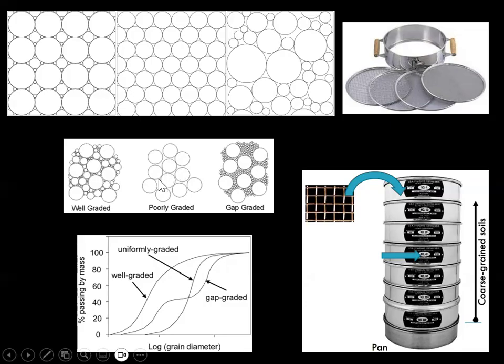So if only we could fill these gaps with more aggregate. We just need a different size aggregate, right? Couldn't you put medium-sized pebbles in there to pack that? But if you zoom in on that, sort of like a fractal animation, now you run into the same problem an order of magnitude down. Now you've got gaps between those gaps. So do you see what this is leading to? You really want a whole variation in sizes. You want your coarse aggregate, your pebbles, your little sand, and so on all the way down. Now, how can you take a soil sample and know what the mix of aggregate is?